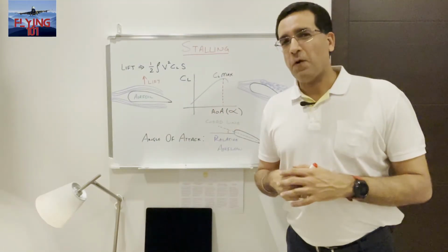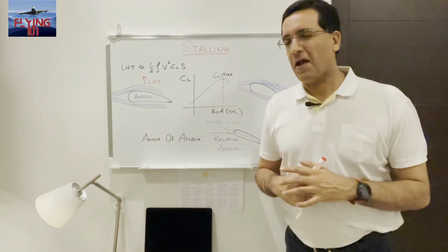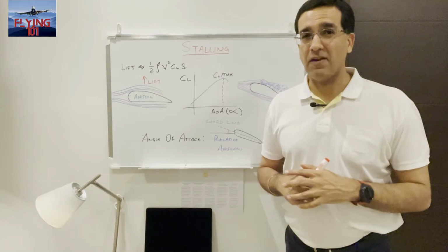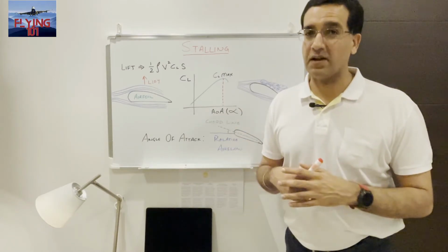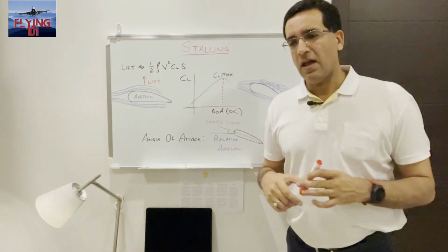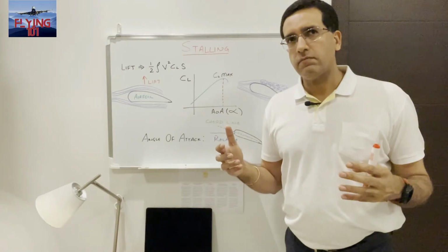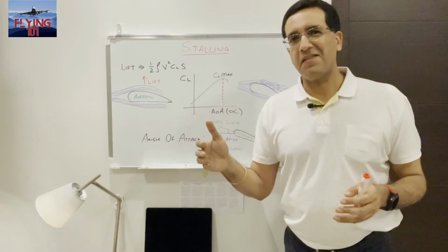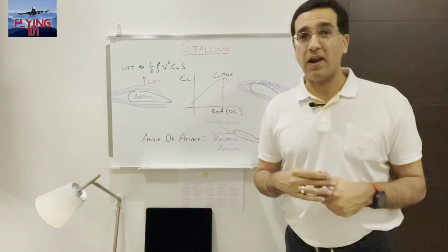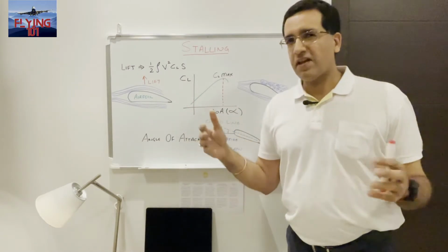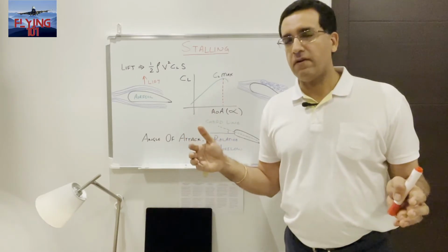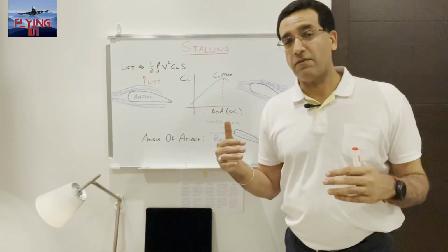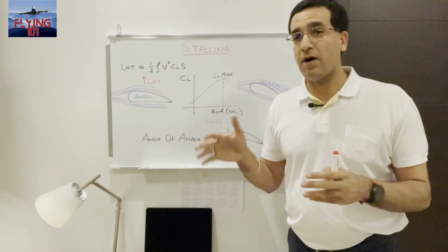All right, so in case you're wondering, how do pilots know when an aircraft is about to enter a stall or if it's in a stalled condition? There's a couple of things. There are some physical signs that would be experienced, coupled with some warning signs that may be on board an aircraft. So the physical signs that could typically be experienced when an aircraft is about to enter a stall or is in a stalled condition is the buffeting of the airframe.